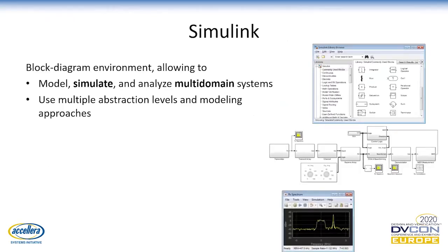Now let's move to Simulink verification, or Simulink-based verification. Let us start with a few words about Simulink, as not everyone might be familiar with it. The first thing that you notice when you use Simulink is that it's a block diagram-based environment. It allows you to model, simulate, and analyze multi-domain systems. And as I said before, with multi-domain I mean really digital, analog, RF, and software all together if needed. Modeling can be done using multiple abstraction levels, from transistor level up to algorithm and mathematical level.